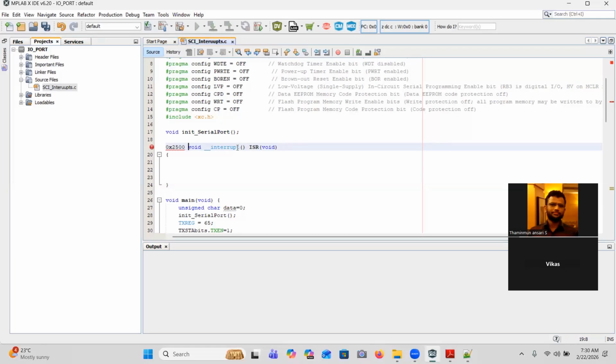When you compile it, it will generate a binary program, zeros and ones. In those zeros and ones, these things are embedded. When the interrupt has come, at memory address 04 they will have a branch statement to 2500. So whenever that interrupt happens, they will come to memory address 2500. In 2500, what do we have? As of now, we have nothing.